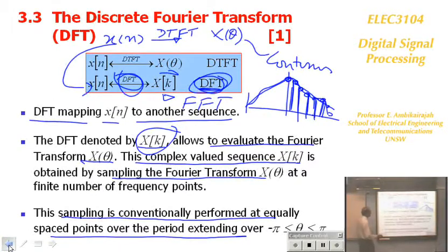So, you want a discrete Fourier transform of a signal, you take the signal, write an equation, and you evaluate that, you will get the discrete Fourier transform at different positions k. K could be starting at 0, 10 Hertz, 20 Hertz, 30 Hertz, 40 Hertz, and so on. You could ask me a question, why does it have to be 10? Can it be 12? Yes, it can be 12. If you start with 12, then it's 24 Hertz, 36 Hertz. Equally spaced. You can't have 12 and 25, okay? They have to be equally spaced.